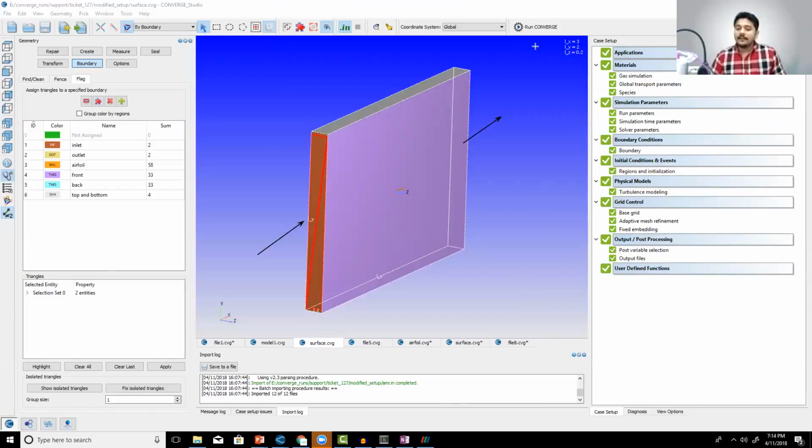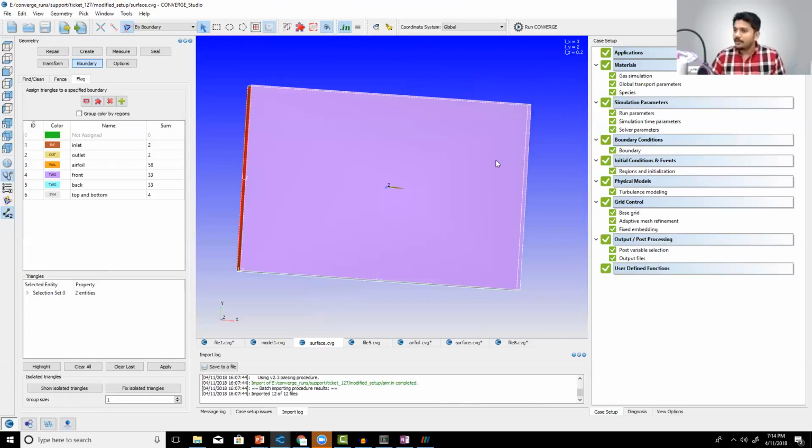So when you do this, you can use this information. Let me just go back to this particular layout. The first thing that I do is take my CAD geometry and convert it into a form so that I can create my computational mesh. Then I set up, for example, what my materials are. And then I set up my simulation parameters, meaning how long the simulation should run.